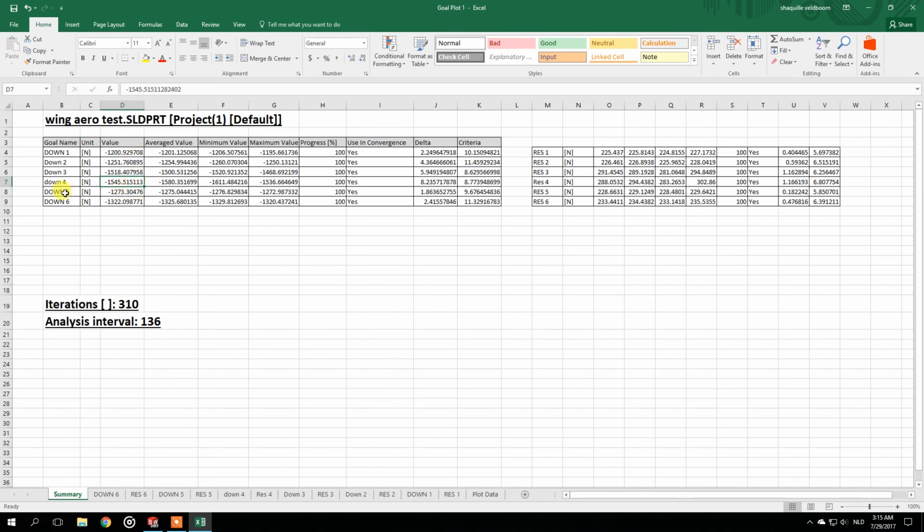So the one that has a curvature that goes towards the front of the car is also creating less downforce, but it is still creating more downforce than this version right here. So I still need to figure out how that happened and why there is a difference between these two, but we will see it in the CFD, I guess. So another thing is that even though this version with the curvature towards the front of the car and this one have pretty big differences in the amounts of downforce that they're producing, the air resistance that they are creating is very similar.